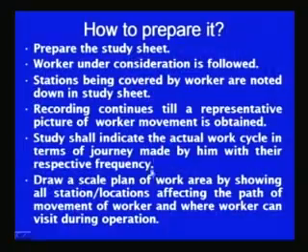And not only the way by which and the sequence in which movements are taking place is recorded, but also their frequencies are noted down. Then using these inputs, which indicate the different stations being travelled by the subject and the frequency of travel between two stations, this information is recorded in a scale plan of the work area.